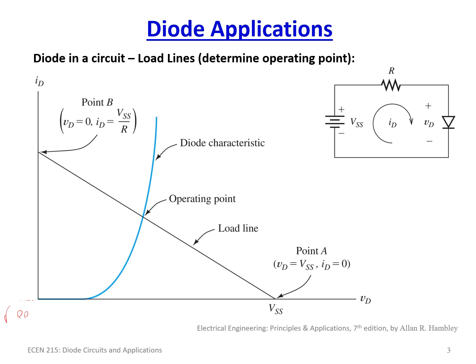The reverse bias region, which we're not actually interested in. We're only talking about the forward bias region, because if you pay attention to this circuit, there's no case where VSS is positive that this diode is going to be reverse biased. So what we're looking at is the intersection. Excuse my poor drawing here. We're going to look at the intersection of the diode characteristic line with what is known as the load line. So we have VSS